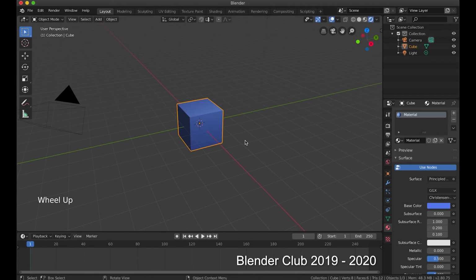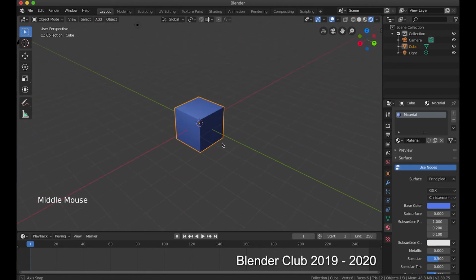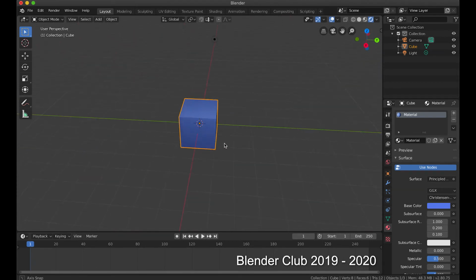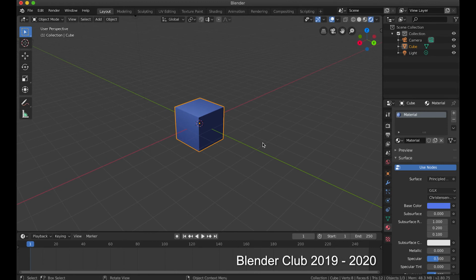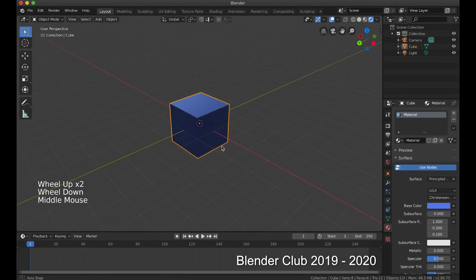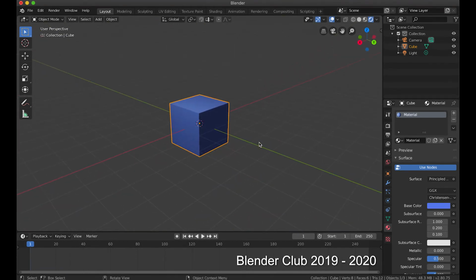There are 2 main render engines that Blender uses to render an object. The one that we are currently using is the default engine Eevee, which is similar in principle to a common game engine like Unity in that it takes shortcuts with lighting in order to decrease the time required to render each frame, which is why we are able to view the full quality of the rendered cube in real time, even when we rotate the view, for instance. Eevee is useful for any projects that don't require photorealism, such as a long-form animated series which needs to be produced efficiently, or a generally low-detail image, such as low-poly art. However, you can also use Eevee as a test engine to get a basic idea of how something would look with a material while you model or animate, then do the final render using the second main engine, Cycles.